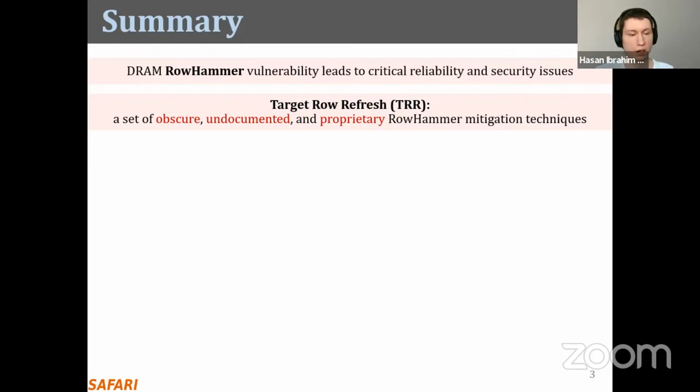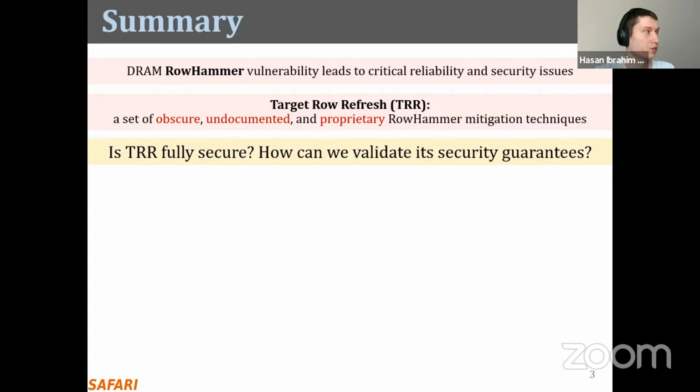So basically, there are three major DRAM manufacturers, right? Or we can count some more maybe, but all of them implement some sort of RowHammer protection mechanisms inside their DRAM chips, and they are not documented, or their implementation details are not exposed in any other way. But I guess they all call them TRR mechanisms. At least this is what we will call these in-DRAM RowHammer protection mechanisms in this presentation.